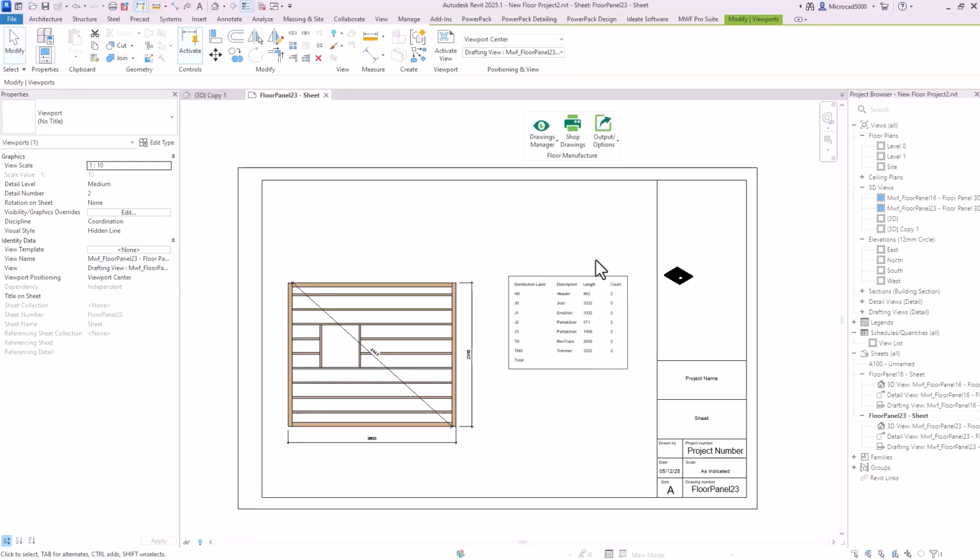Can you add hangers? Yes, you can add those, but they only work in the analysis on rectangular lumber at the moment. So if you wanted to place hangers on, say, plywood web joists or lattice joists, then you can add them, but you'd be adding them in Revit and not in the analysis package.